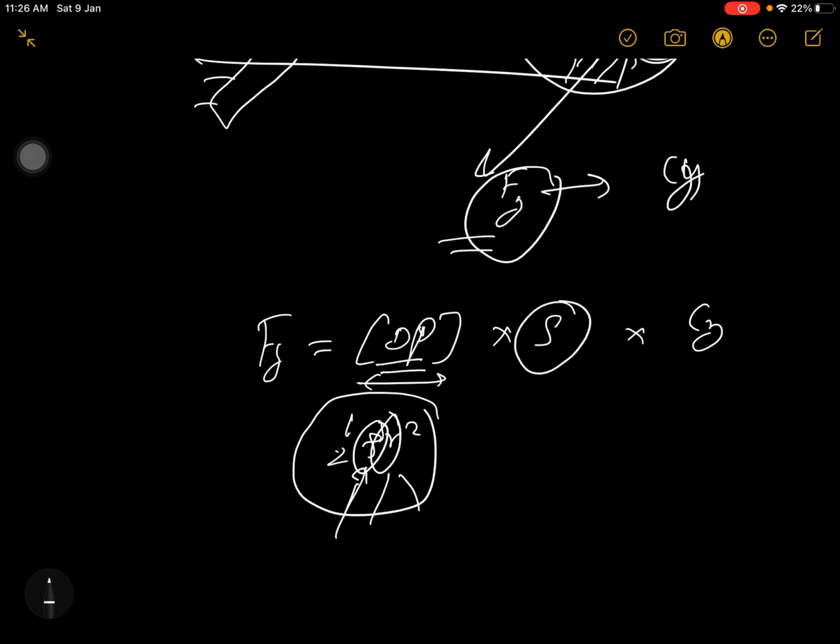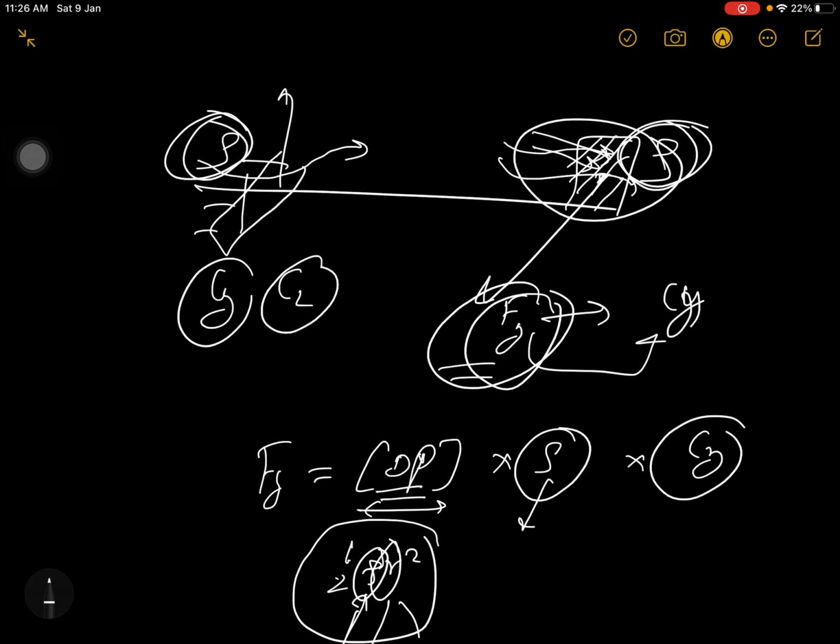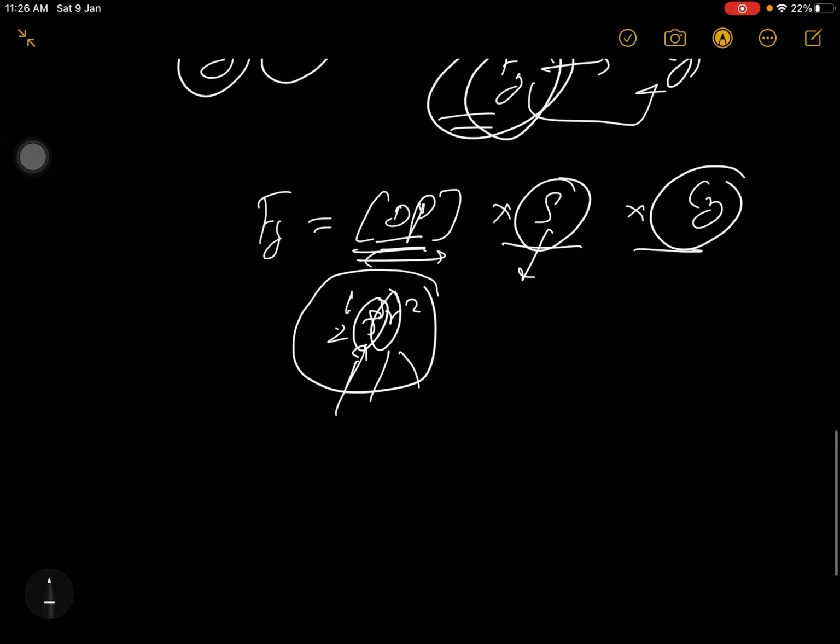Now what is planform area? Given directly. Now what is Cy? I explained. For every force we have its coefficient of force, right? In case of lift we call this coefficient of force CL. Now, by multiplying these three terms you can find your Fy.